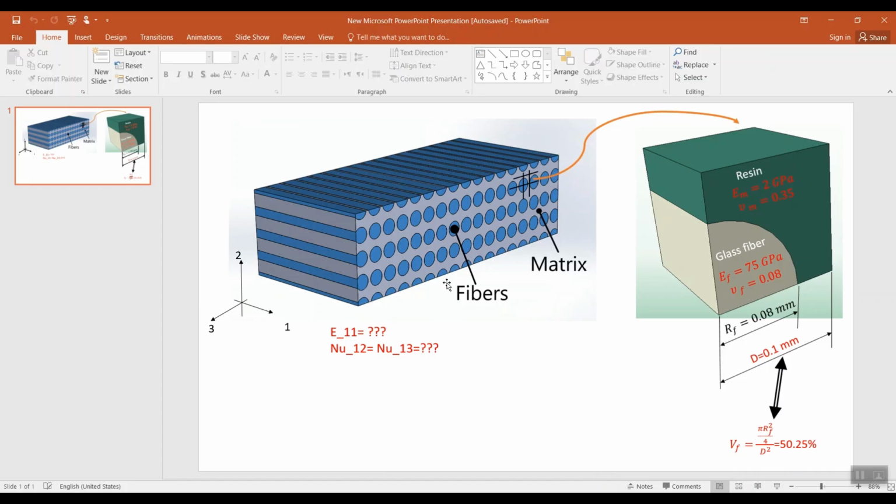So this is the Young modulus that we obtained for this FRP. Let's check it back. We had 35 gigapascal for the glass fiber and 2 gigapascal for the epoxy resin, but E11 is almost 38 gigapascal.